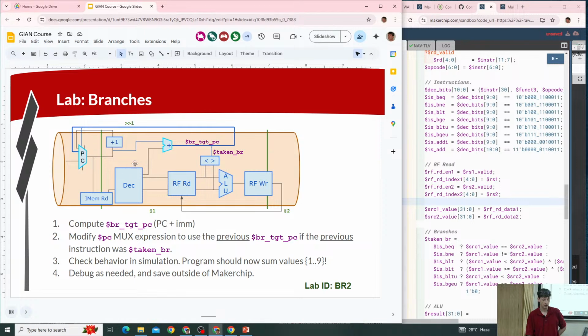And you can tell from the logic diagram the way I drew it, right? We're taking the decision made by this instruction in stage 1 and applying that to the PC of the instruction after. So if this instruction in stage 1 is a branch, the instruction in stage 0's PC should be the branch target of this guy. Okay, so make sure you're hooking this up with the right timing relationship.